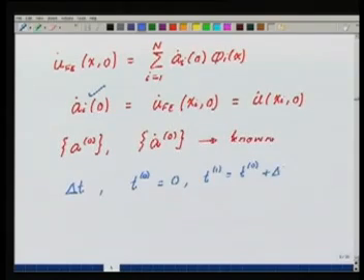I am taking uniform time steps, but you could change the time steps, and you should, if the solution shows very little activity, that is, it is very smooth with respect to time in a particular part of the time interval, where I can use large time steps. But if it is showing some very sharp temporal behavior in some time interval, there I should use smaller time steps.